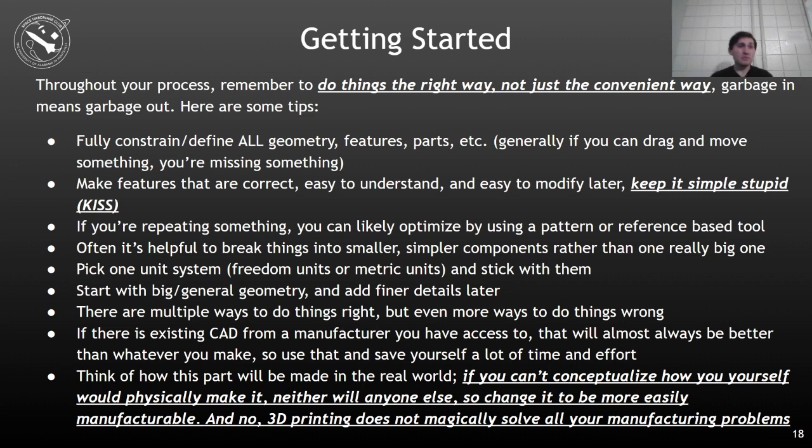So, another thing, this is I'm guessing not, but is anybody here like computer science or software-ish? One thing you may have heard at some point is basically if you're repeating any chunk of code, any chunk of a design of something, you're typically doing something wrong and can optimize it. So in here, there are different things like patterns that you can do, kind of similar to how in code you might have some sort of a loop. Here you can do some sort of a pattern to do something. So rather than going and adding features for like 500 holes on some sheet of something that a bunch of screws need to go into, you can just make a pattern and get it done in 30 seconds rather than spending the next 8 hours wanting to die.